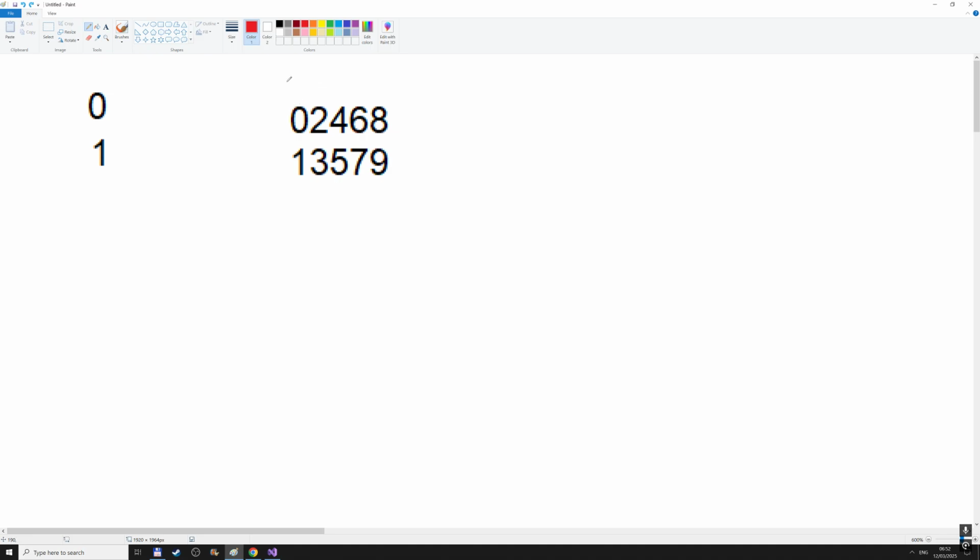So when you write a 16-bit value at this address, it writes this pixel, pixel 0. When you go to the next 16-bit address, it writes the one below, then goes above to the next pixel, and so on. That's how the video RAM is. So that could make things a bit harder. But that means when I read a 32-bit value, so that I do 2 pixels away, it's gonna read this pixel and the pixel below.